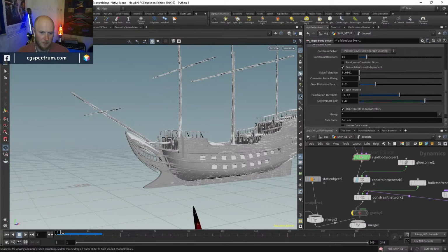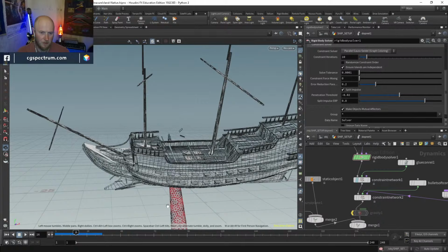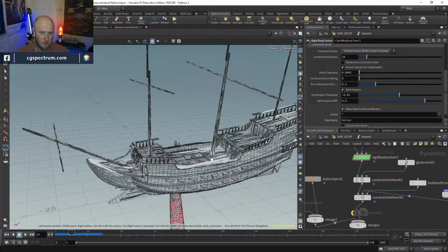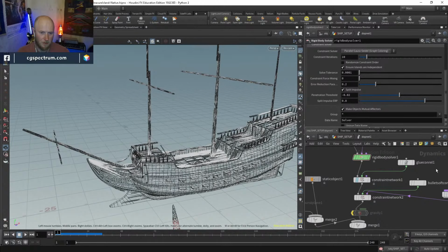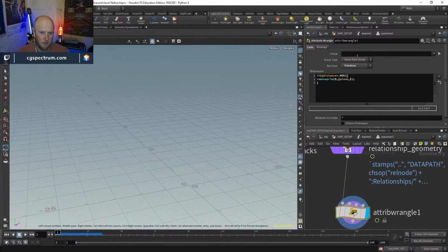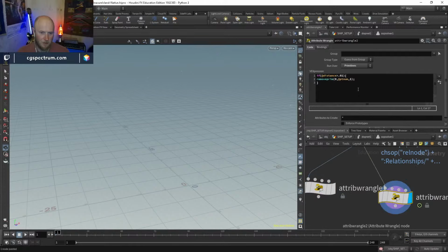So, you can probably see those constraints getting deleted. See how they disappear almost immediately as that thing touches it. Probably what I want to do is just increase that value. At the moment it's very low. Let's do greater than 0.01. You could also change what you're using to delete them by. So yeah, perhaps I'll just save this one and try a different one.